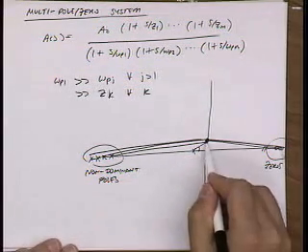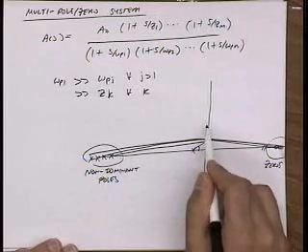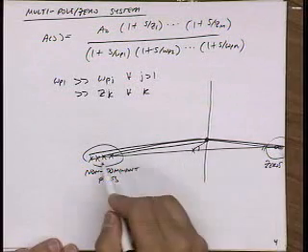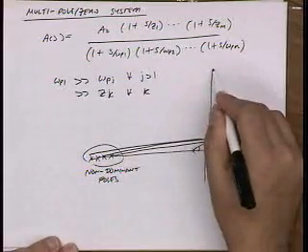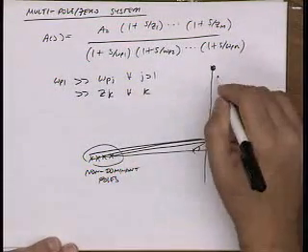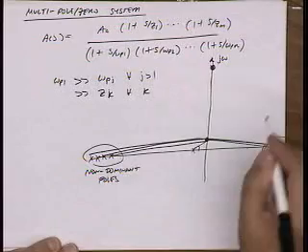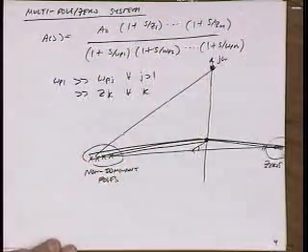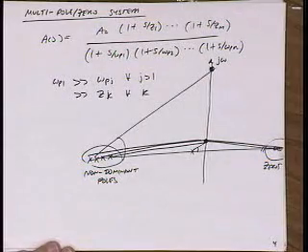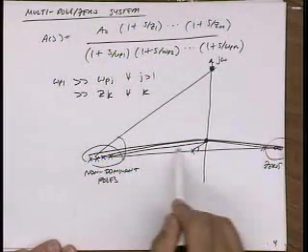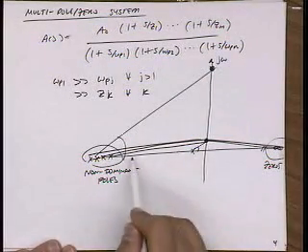What we care about is phase, right? So as we go up higher and higher in frequencies, these poles contribute phase, right? So if I go all the way up to here, this is my j omega axis, then now you can see that, aha, these poles are contributing about 45 degrees. But over here, they're contributing very little, right?